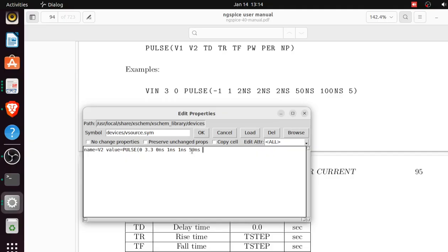The period, so how long it will take to complete a cycle, the up and down. For the downtime, I want to make it equal, so it takes 1 to rise, 1 to fall, then 50 to remain constant, so that's like 52. For the next 52 nanoseconds also, let it be reading 0 before the subsequent 52 nanoseconds. So at the end of the day, the period is 52 times 2. Is that looking like 104?